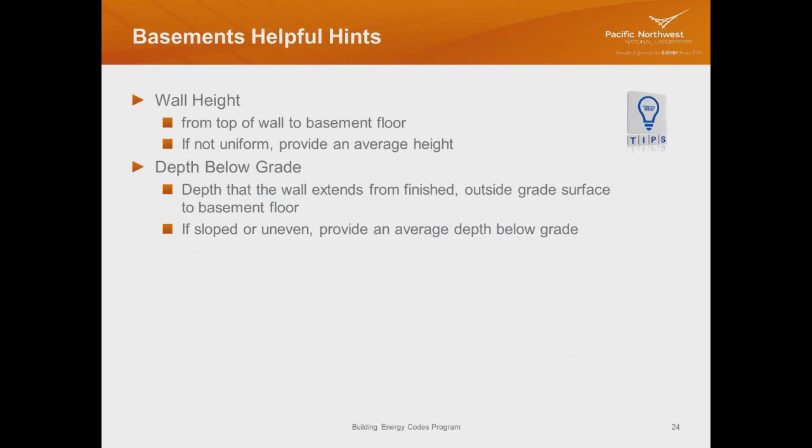So some other helpful hints. Entering your wall height for a basement: you are taking from the top of the wall down to the basement floor. Typically basement walls are 8 or 9 feet high. And for your basement wall entry in REScheck, it asks you for a couple more entries because it also needs to know the depth below grade and the depth of insulation.